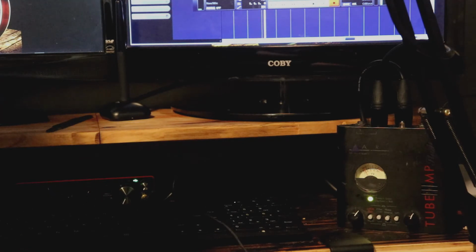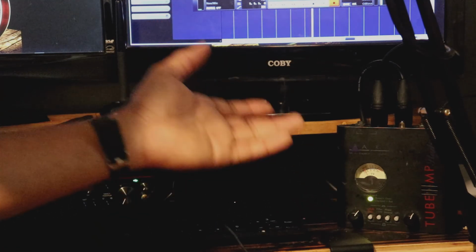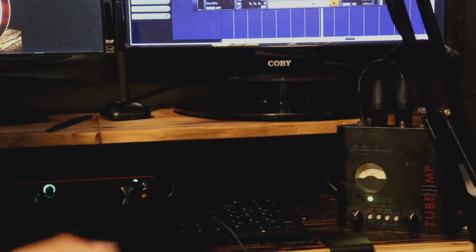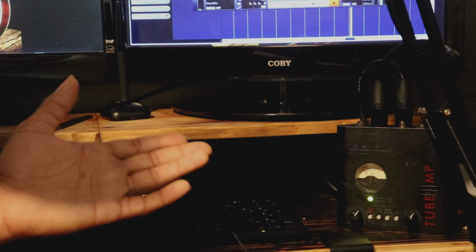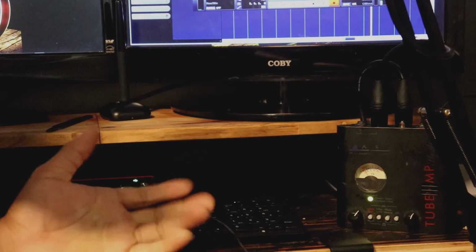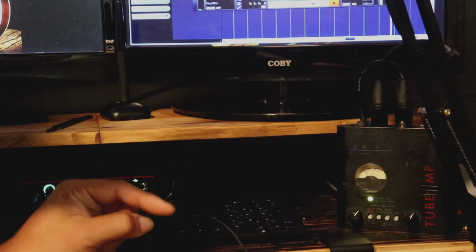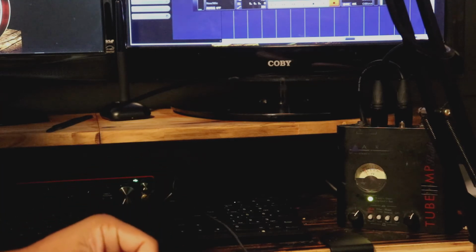The passive EQ would work great because, one, it doesn't need a power supply. All it is is just some RC junctions, some resistor and capacitor junctions. Also, this amp makes enough gain to where it could drive that RC network without losing any substantial voltage swing. So this amp is strong enough to drive an RC circuit. And that would give me the ability to tune and tweak my voice to my preference as I make these animated videos.